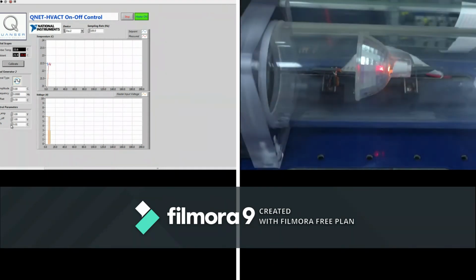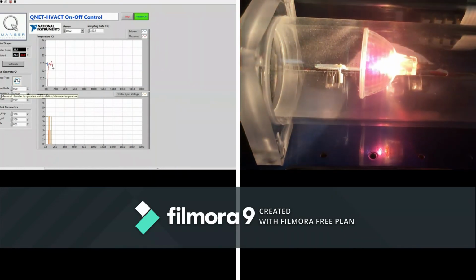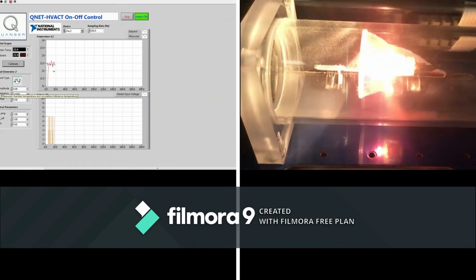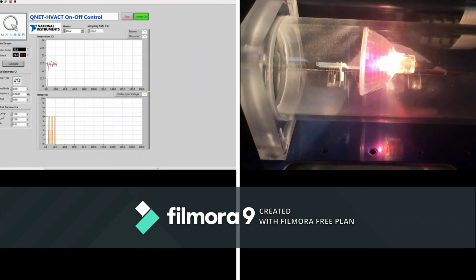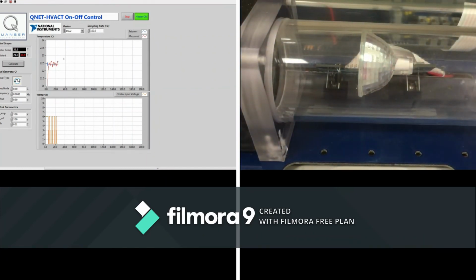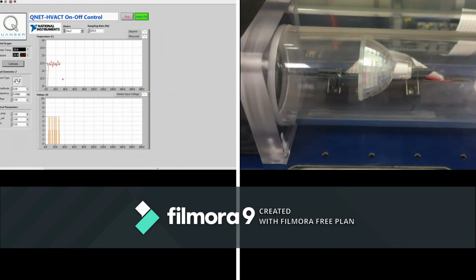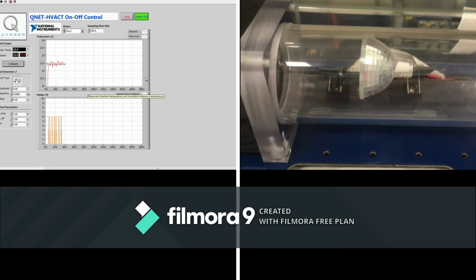So because of this 0.01, very small value, the heater will be on and off, on and off, on and off, because we have the limit of 0.01 Celsius. This range is very small. But if I increase it, I will wait from 0 to 30 seconds, for example, and then I will change this to 1 as mentioned in the manual, and we will study the effect of this high value.